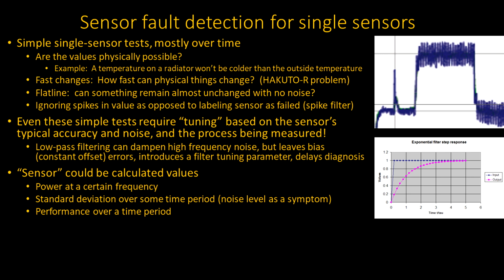Sometimes when you get this rapid high frequency noise, it actually indicates a process problem. A classic example of that would be, say you've got a fuel flow going into the pump, the pressure could be fairly low, and it's quite possible that you'll end up getting vaporization at that point. You get a bunch of bubbles of whatever the fluid is, in the gas phase.